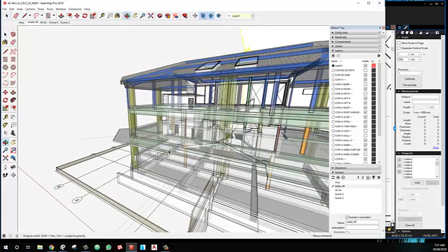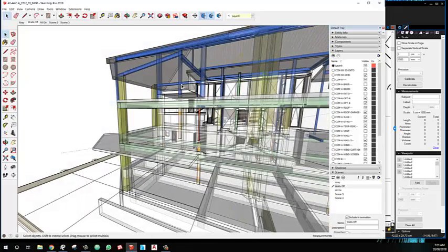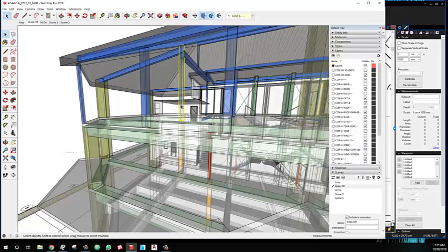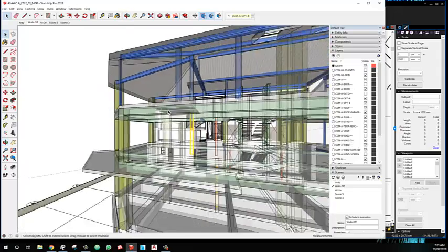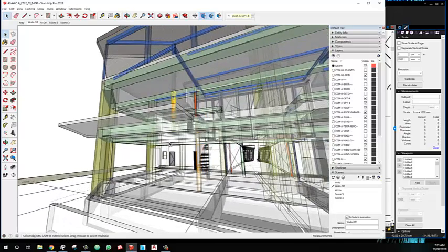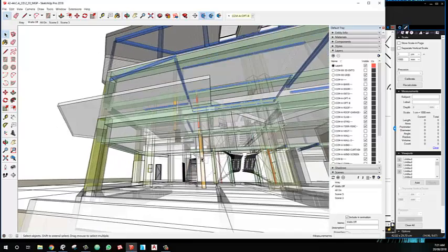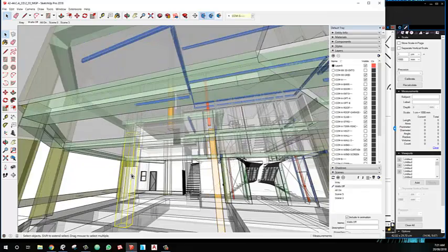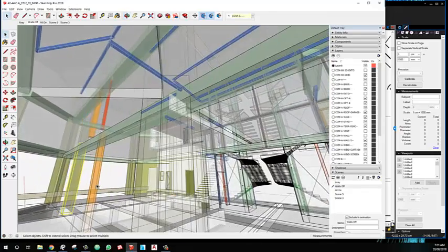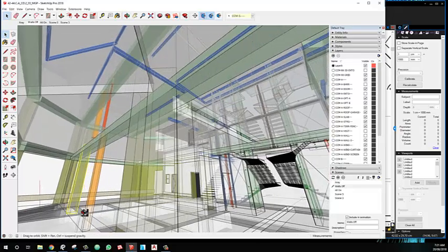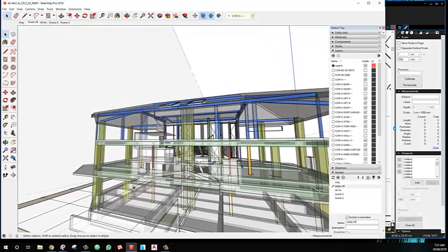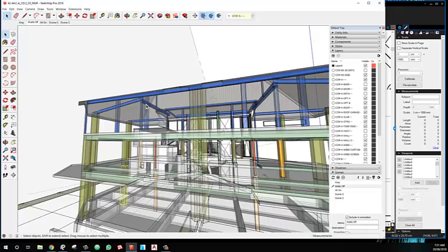This post here is the one that comes with the roof. We want it to continue on the ground floor in the same position, and then in the basement it moves according to you on site. It's not a big drama if we create a new post because we have this column falling on top of the beam, and then there is some foundation aligned with the beam. But we want this to be confirmed and amended so people can order the steel on site.